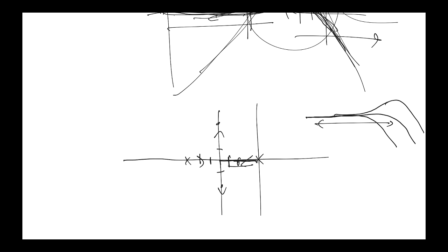And it'll move to the right, but while it's peaking up, you're not getting a faster response from the perspective of settling time anymore, and you're just getting more oscillations because you're getting less damping. So you can only think of a relationship between pushing the crossover frequency to the right and reduction of the settling time until you get peaking in the response.